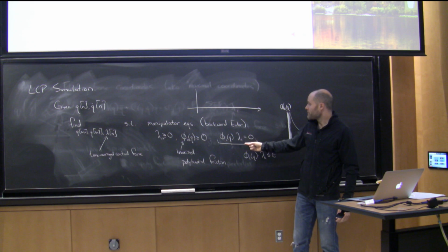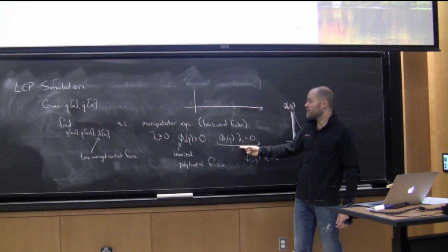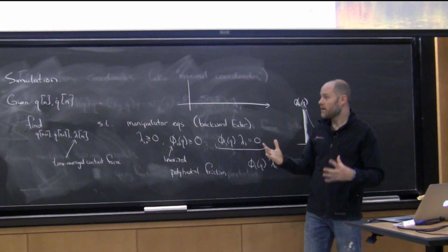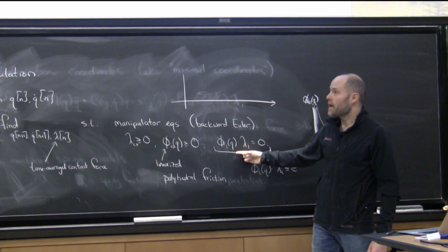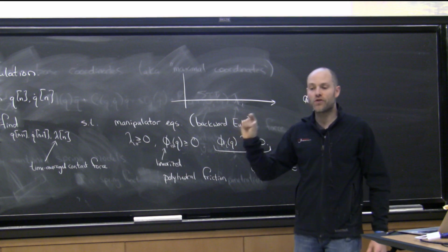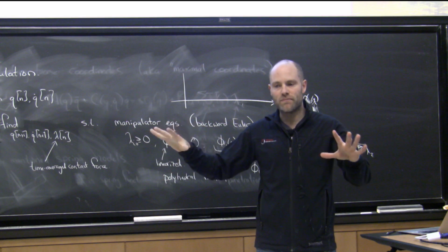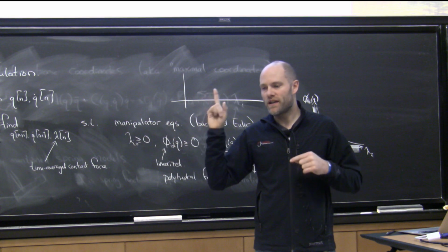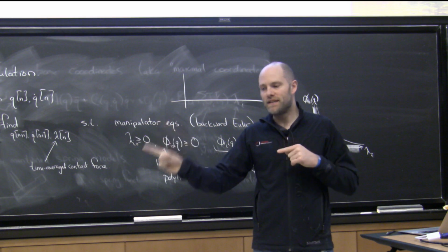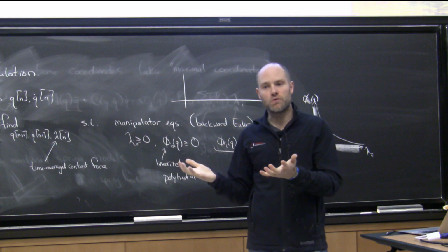One of his key observations was that if you write down the sums of squares conditions for Lyapunov stability using these types of equations, because of the way that the contact forces enter linearly, you don't have to solve the combinatorial number of possible contact sequences. You can think about the implications on V dot of each contact individually and still say something about their contribution in joint.